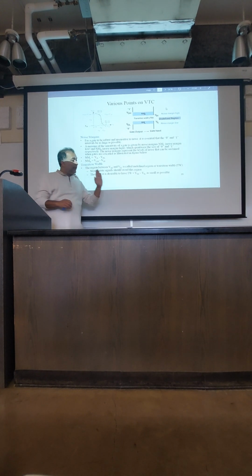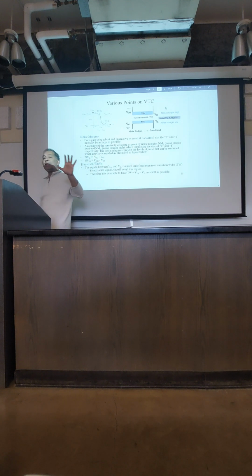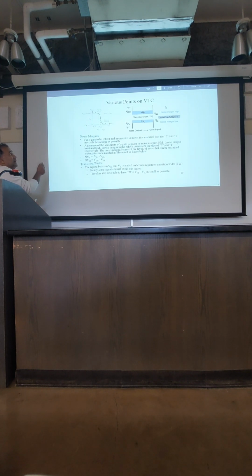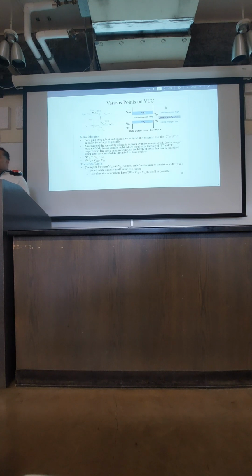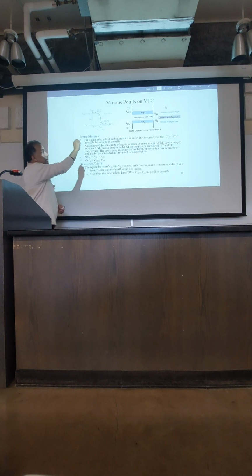And for an input voltage of minimum and above, we want to consider it as a high input and the corresponding output should be low, right? So at the lower range of the voltage and at the upper range of the voltage, there are two valid ranges here and here, where we consider that the signals are valid. Outside this range, during the transition width, the signals are not valid, it's the undefined region.